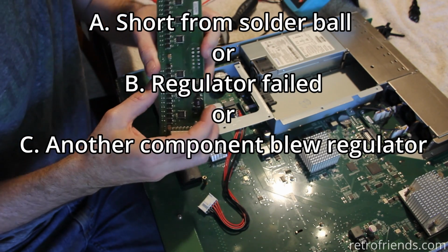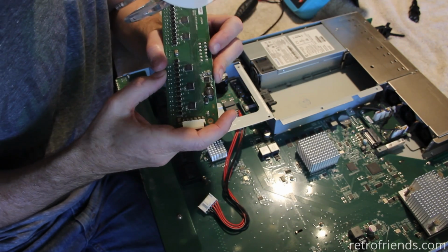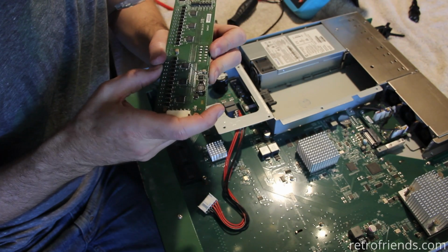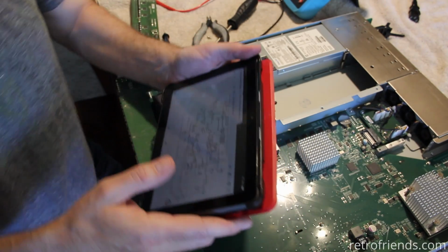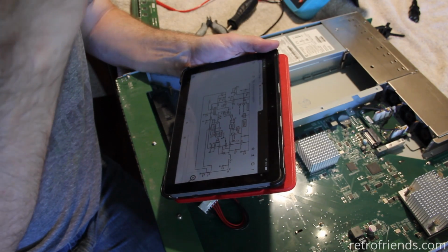I mean, it looks kind of brassy, and that's not normally what solder looks like, because when it gets hot, it doesn't change to a brassy color. But if that solder ball shorted, let's see, it would either have shorted with pin 2 or pin 4.